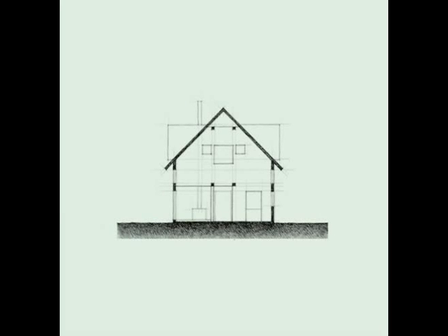We refer to this darkening as poché. Remember that the ground mass is also cut in building sections. The tonal value of the section cut should continue into the supporting ground mass. A second approach is to reverse the value scheme and render the cut elements as white figures against a spatial field of darker values. Emphasize the section cut as well as convey a greater sense of depth. We can also render the shadows cast by the cut elements.